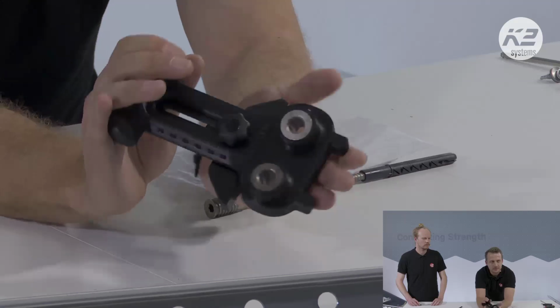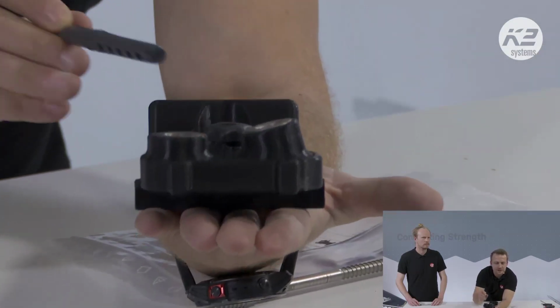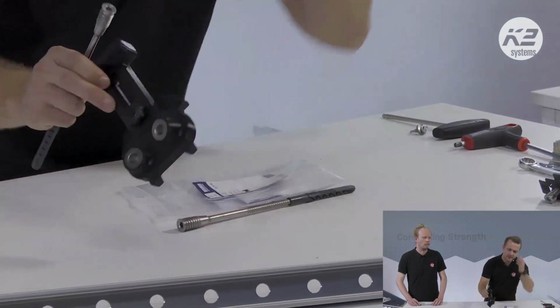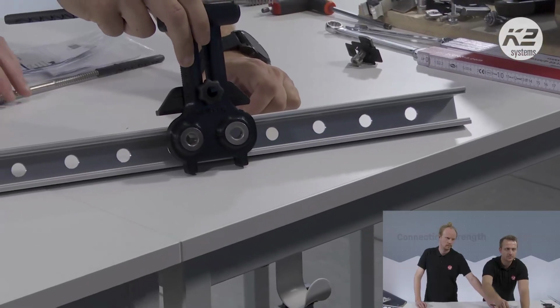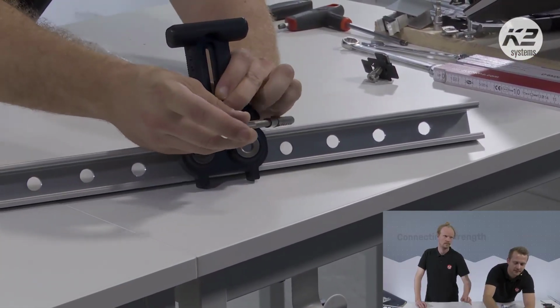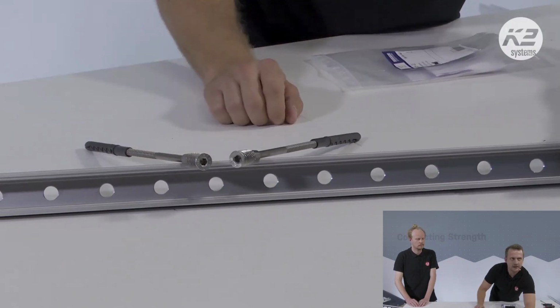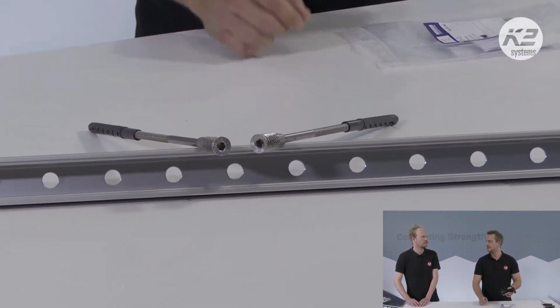And this one is actually a 15-degree angle, because you need to put a hole in the wall at a 15-degree angle with this Schablone here. And then the screws will stick like that, as Kyron prepared over here, like this and like that in the wall. This just provides a better structural fixation in the concrete wall, which is behind the insulated panel, or the ventilated insulation panels.